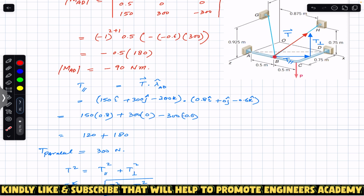Now, how do we find the component of T parallel to AD? That's very easy. We can take the dot product of this T vector with the unit vector along AD. That will give us T parallel. So T parallel is equal to T times the unit vector from A to D. This is the T vector that we have already determined, the Cartesian vector representation of tension T, which is acting from B to H, dotted with the unit vector from A to D.